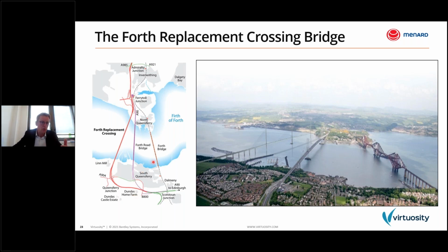Due to this new bridge, it was needed to work again on the road alignments on the north and on the south of the estuary, and especially on the north part, the new access road embankments run over very weak soils made of soft organic alluvial deposit, which were reclaimed many years ago.